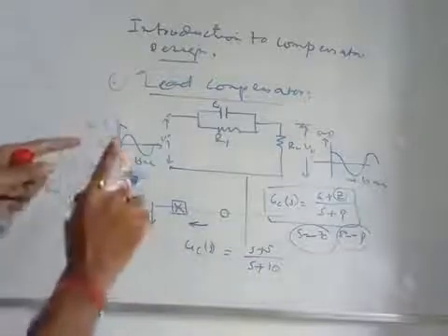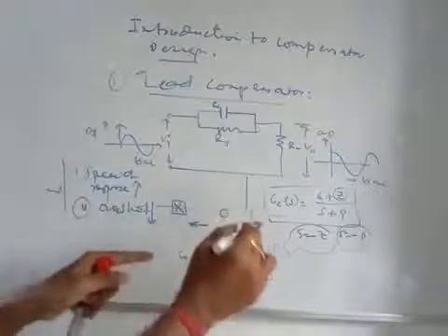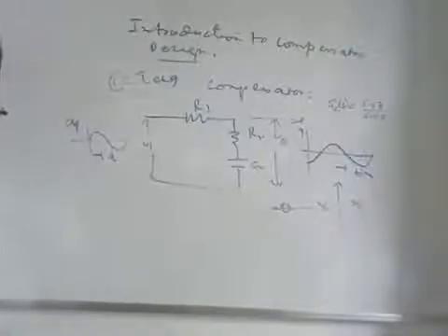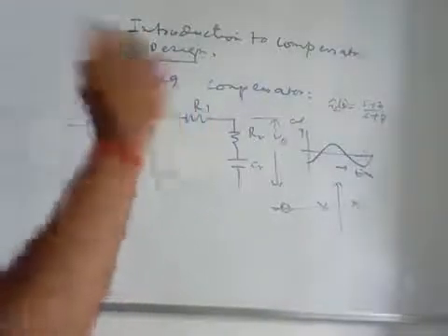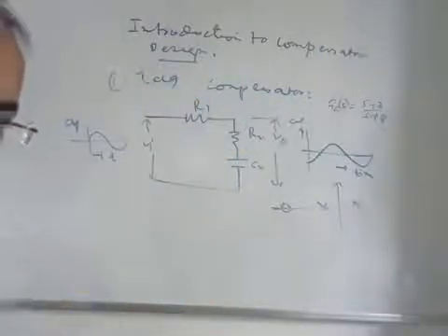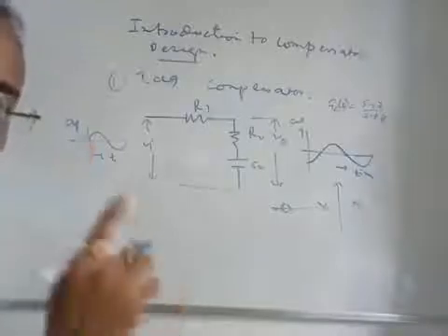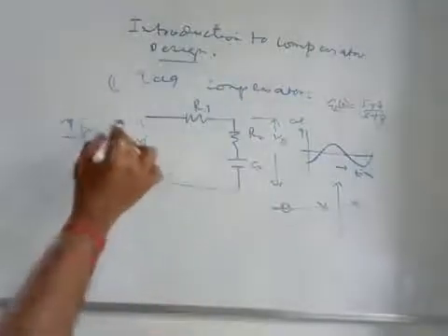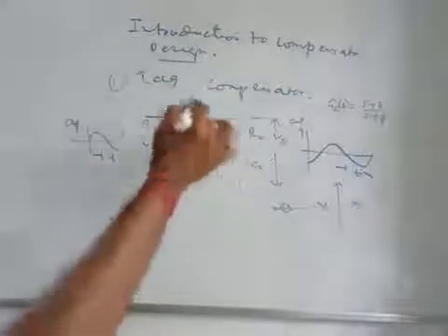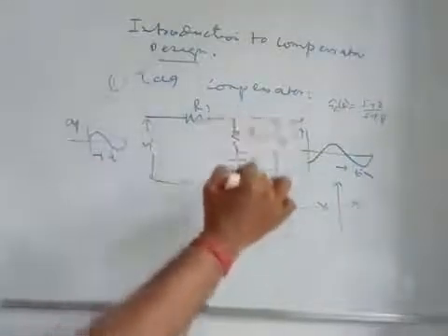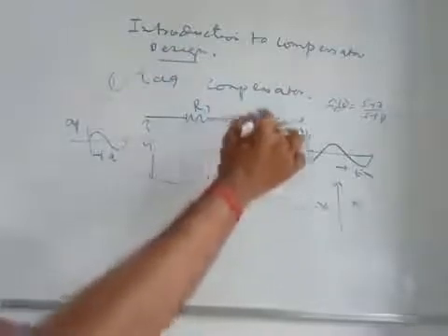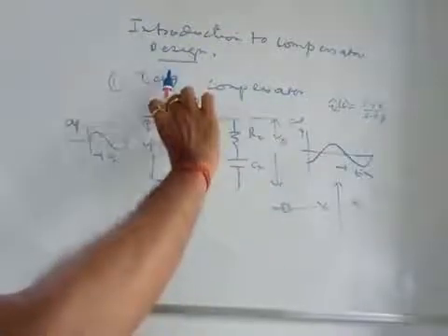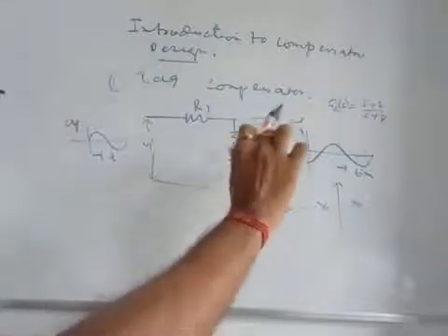Next I will discuss the lag compensator structure, its transfer function, pole-zero form, and advantage or effect. Here you see the lag type of compensator, which is similar to the phase lead type. It is sometimes known as phase lag or phase lead. Phase lag compensator means the phase of the output is lagging once you apply any sinusoidal input of certain phase or frequency at the input side of this network. Here the capacitor block comes in series with the resistor, and in the lead compensator the R and C were in parallel, and the output was measured across the resistance.